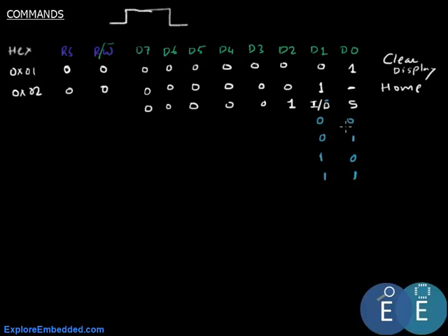the display will not shift. The character which is displayed will not be shifted. So what we mean here is, say a character A is displayed here. Now if we decrement, the cursor would point to the previous location in the RAM, and the letter itself will not shift. Whereas if we keep the decrement option turned on, and if we make S 1, even the letter A would shift back and the screen would become blank, assuming this is position 0, 0.